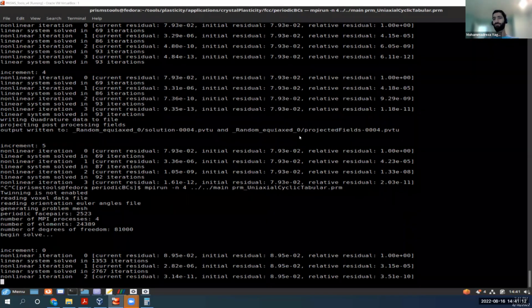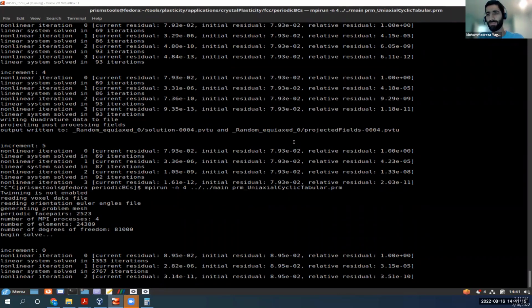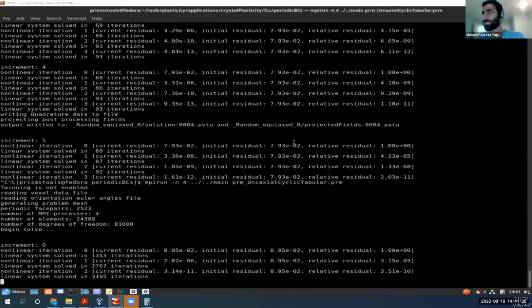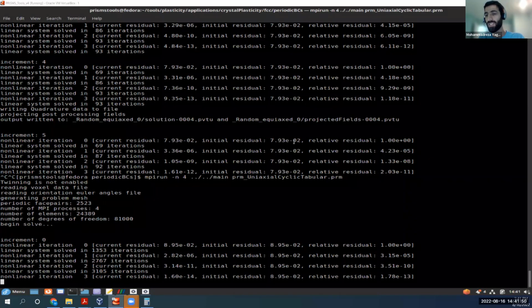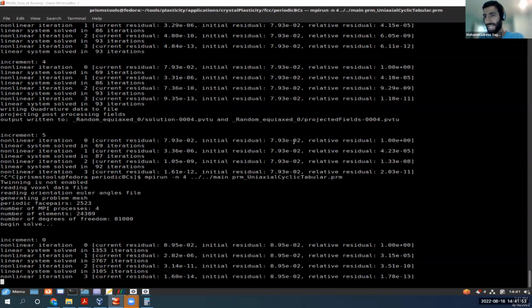I didn't plan to do this, but I think this was nicer. Now you can actually go and find the real simulation files and try to start from there. That's much nicer. I think that would help you a lot. For the majority of the publications that are out there, you can just go and find the input files and see what we used. So you can just read the input file and understand. But I just want to reiterate: read the documentation, read the user-defined material documentation, read the source file, especially update after increment and calculate plasticity.